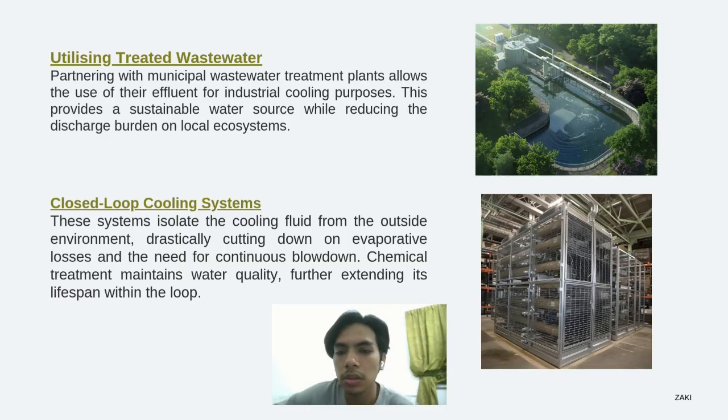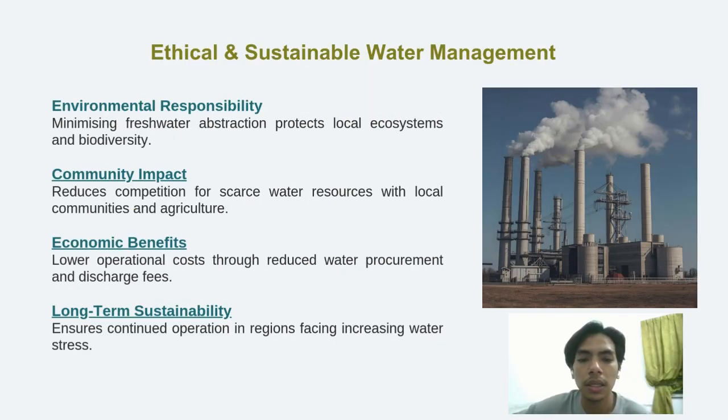Those systems isolate the cooling fluid from the outside environment, theoretically cutting down on evaporative loss and the need for a continuous blowdown. Chemical treatment maintains water quality, thus extending its lifespan within the loops.